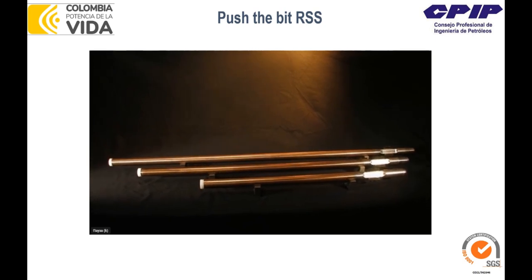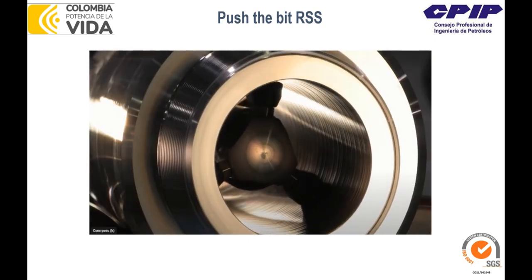Okay, so that was the example of the push to bit system. So again, simply saying, it has the movable pads outside of the BHA, and when the pad is pushed to one side of the borehole, simply saying the BHA is steering in the opposite direction. And this is it. So that was the first generation of the tools in the market, and that's a kind of reliable tool and has a huge meterage drilled with this tool, but it also has some limitations.